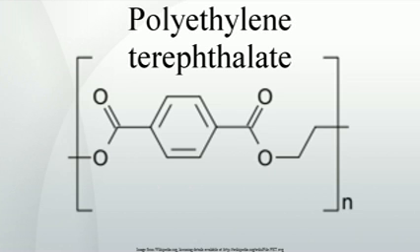High temperatures, PET decomposes above 300 degC or 570 degF. High pressures, extruder speeds, excessive shear flow raises temperature, and long barrel residence times all contribute to the production of acetaldehyde. When acetaldehyde is produced, some of it remains dissolved in the walls of a container and then diffuses into the product stored inside, altering the taste and aroma.